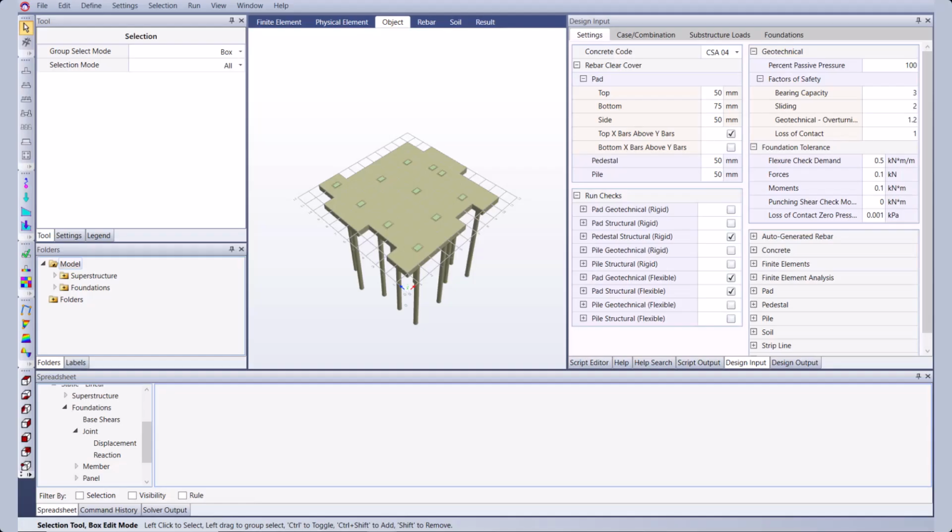We'll show you how the pile soil springs alter the different code checks performed by S Foundation. When we have a model with asymmetric geometry and load distribution, as well as an asymmetric pile location, the deflections produced on the pile cap can result in a failure status for some of the structural code checks performed on the foundation.